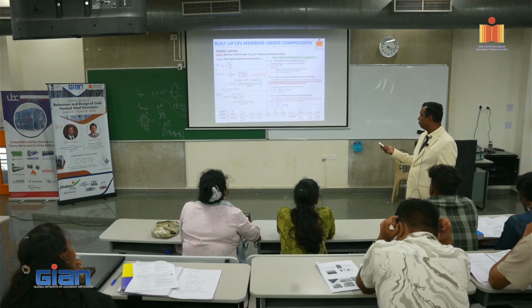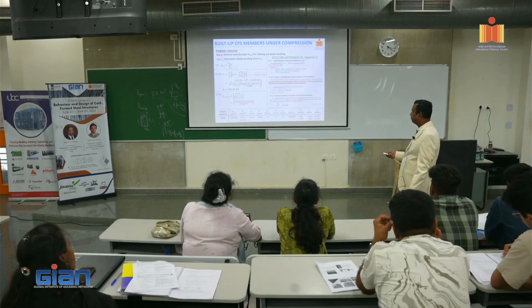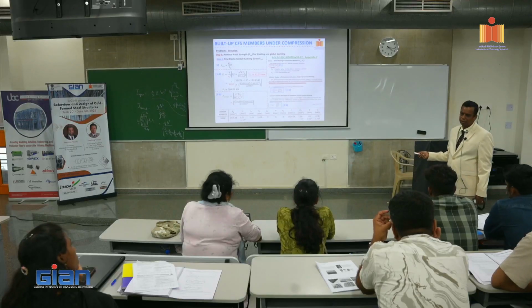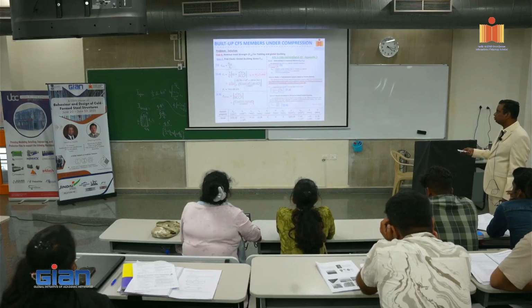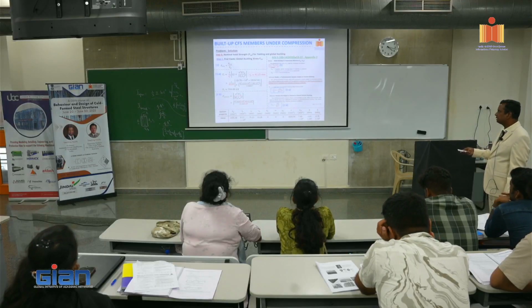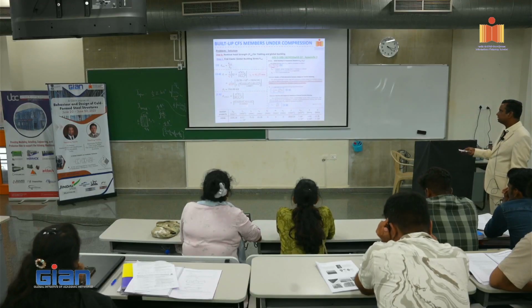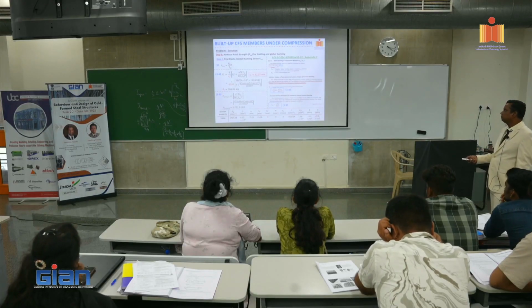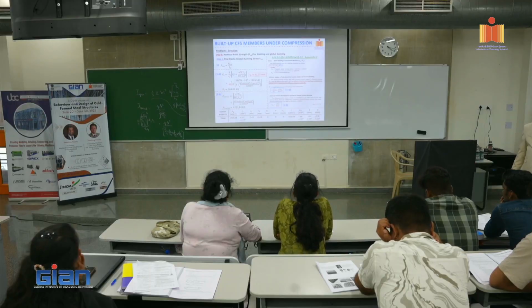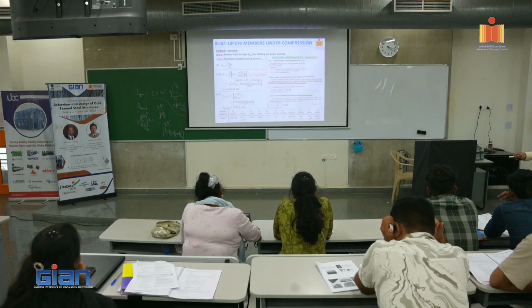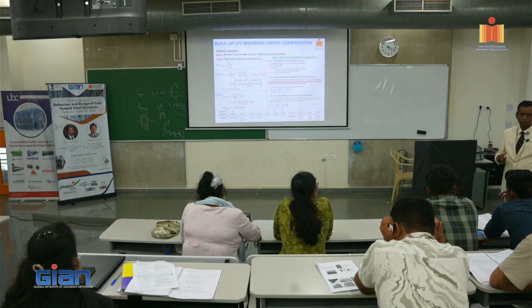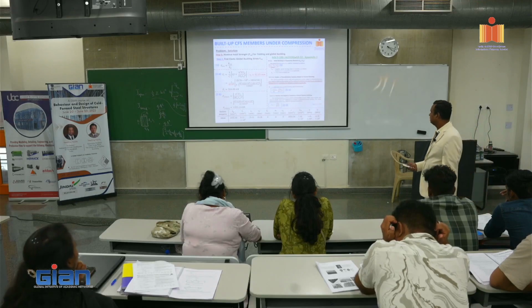So when you do all that, you have to calculate both P critical Ex as well as P critical Ey. So you have pi square into 2.03 into 10 power 5 into 8.12 into 10 power 6 divided by 1 into 3650 the whole square, right? So we get 1221.14 kilonewton, right? Any questions on this one? If we don't have any questions, we'll go to the next slide.